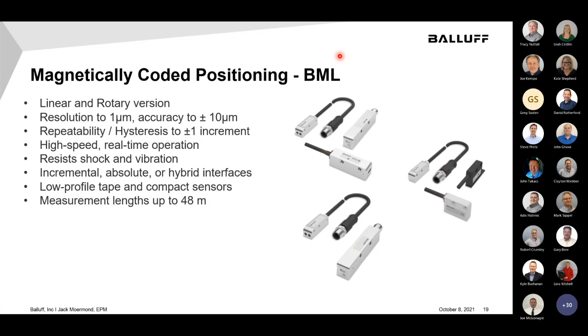Tim had a question here: how stable is the measurement value using a capacitive sensor, given that environmental conditions, i.e. temperatures, can have a major impact on capacitive sensors? This is true. Temperatures can affect capacitive sensors. So that's one thing that falls in those application questions: find out what the temperature rating is so that we can try to determine what that effect is going to be.